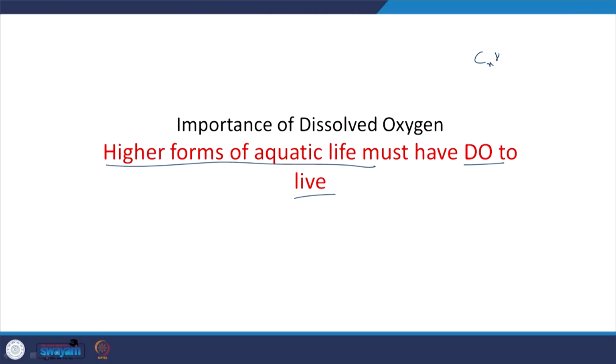So, how is it that dissolved oxygen is going to be affected or decreased? One is if a DO-less stream comes into play, or if I have a lot of organics, C6H-something, let us say a simple representation of human waste, right. I ate something and I let it out, and if I let it out into nature, what is going to happen? It is going to take up oxygen and go to, let us say, CO2 and H2O or different byproducts. So, we are using up the dissolved oxygen in the aqueous phase, and thus we are creating anaerobic conditions, or no oxygen conditions, in our environment, which is unhealthy. That is something to keep in mind.